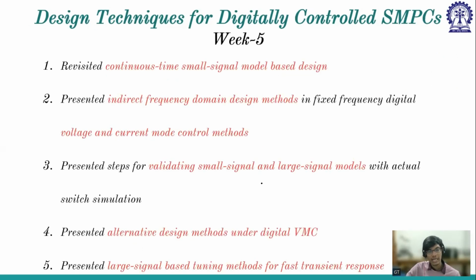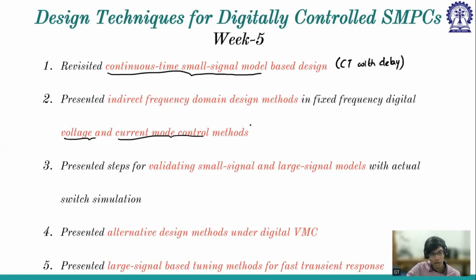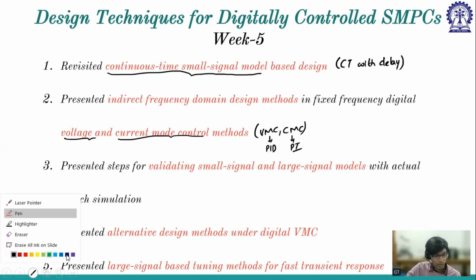And week 5 is the design techniques, where we discussed controller design. To start with, we discussed the continuous time small signal model design, which means the continuous time with delay, because we came to the conclusion that it is simpler and it is sufficient. And then we discussed the indirect frequency domain design in voltage mode as well as current mode control. So we designed the PI controller as well as the PID controller. In voltage mode control, it happens to be PID, and in current mode control, it happens to be PI, depending upon the requirement.